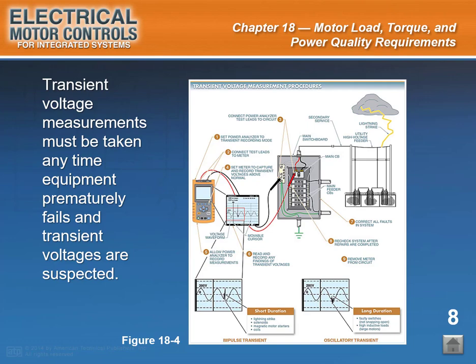Transient voltage measurements must be taken anytime equipment prematurely fails and transient voltages are suspected. See Figure 18-4. Transient voltage measurements are taken to verify that surge protection devices are working.